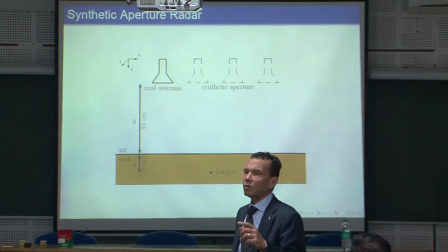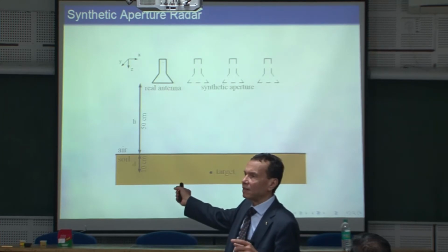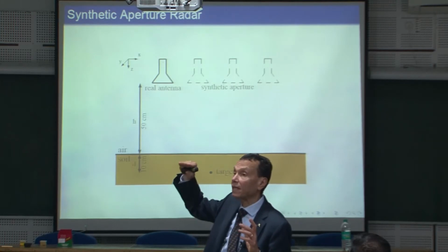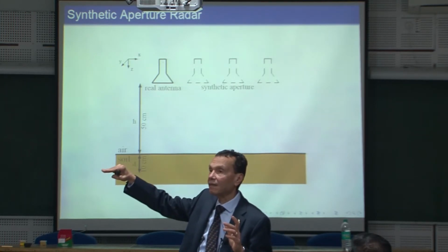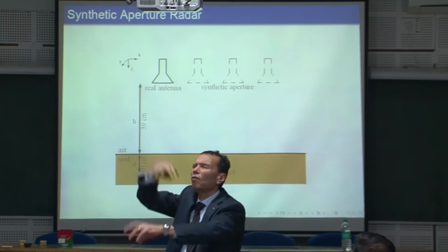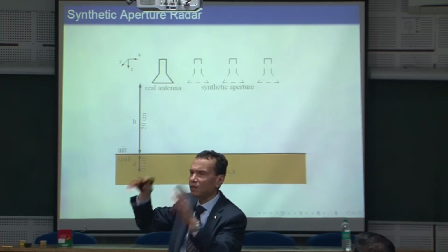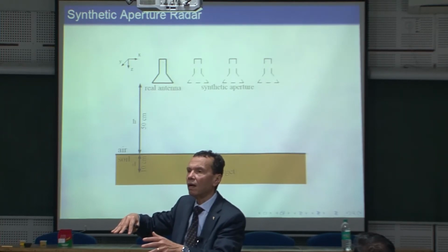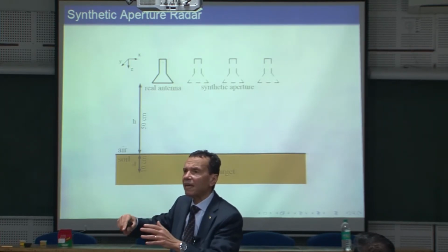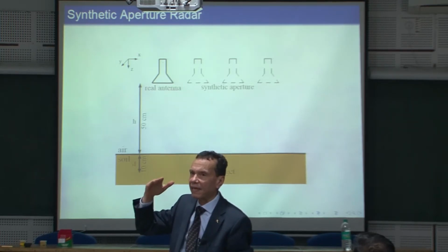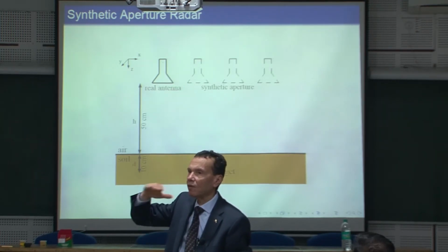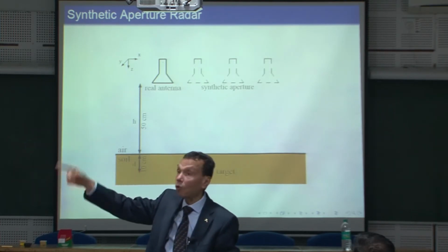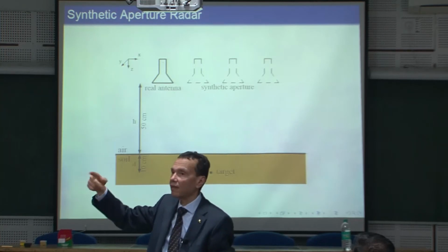Okay, so I have my network analyzer, and this is taken care of in the calibration process because I can calibrate up to the mouth of the antenna. So all this complication is put in the error 2-port. So you do a normalization or you do a TRL cal at the mouth? No, I will put my calibration reference plane on the mouth of the antenna, so that I take all the multiple reflections inside into account.